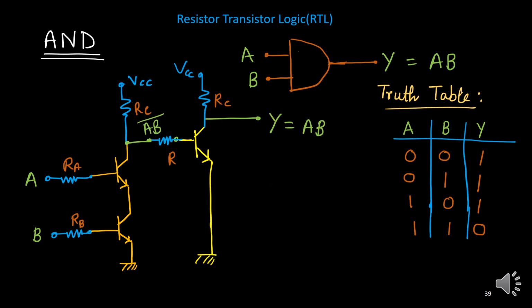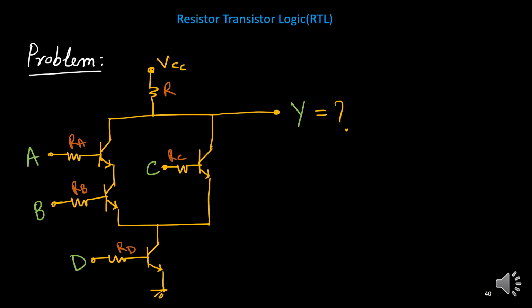So what is the AND gate? How to design it? From this NAND gate, if I introduce one NOT gate followed by this one, we'll get the AND gate. That's simple. We have already discussed these things. Whenever the transistors are in series, we'll get NAND first. We'll get the complement bar here. Then to remove this bar, we need to put another NOT gate. So the negative of this one, this bar is removed, we'll get only AB.